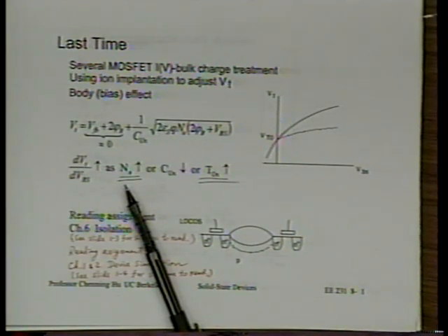So in MOS transistor technology, CMOS technology, when do you get very large threshold voltage? Can you think of any cases when the threshold voltage is unusually large? What's that? Isolation. Excellent. This is called the field threshold, the field transistor threshold. So the field transistor has particularly strong body effect.